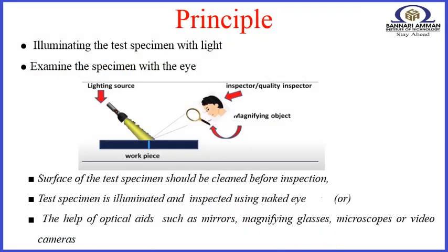The basic principle of visual inspection is that the eye can perform accurate inspections to detect size, shape, color, depth, brightness, contrast, and texture. Visual testing is essentially used to detect any visible discontinuities, and in many cases, visual testing may locate portions of a specimen that should be inspected further by other NDE techniques.